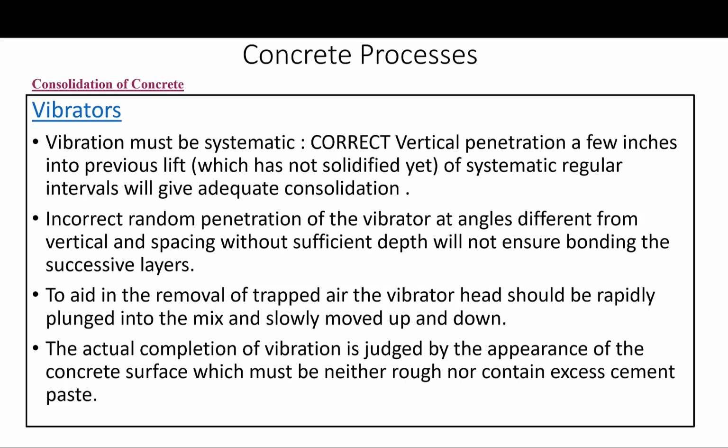Incorrect random penetration of the vibrator at angles different from vertical and spacing without sufficient depth will not ensure bonding of the successive layers. And again, this is something engineers and supervisors in the field must make sure happens. Otherwise, the results are not good. And I have seen a fair share of this investigating certain structures about poor consolidation and poor vibration.